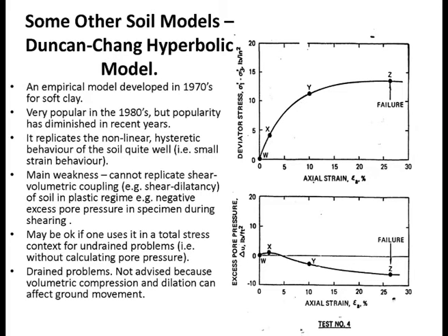When you want to use effective stress and you want excess pore water pressure, this model cannot give you the correct excess pore water pressure. Basically, if you use it before yielding occurs, for example before the peak strength, I have used it before peak strength, it works okay because there's not much significant pore pressure generation, so you can still get away with it. Actually, I dispute that the hyperbolic model is totally useless. I find it quite useful in certain cases, but you have to apply it intelligently.